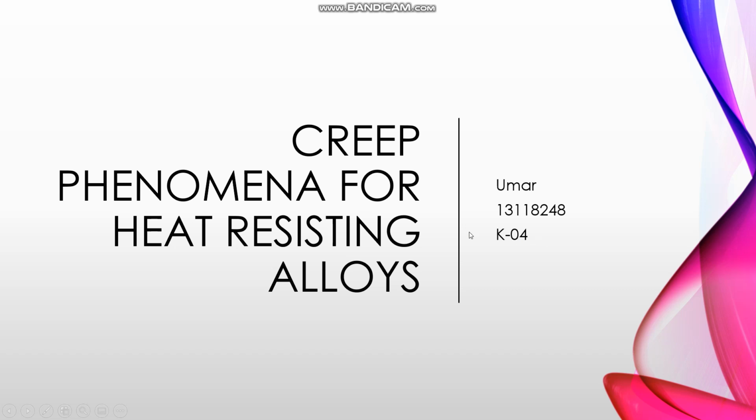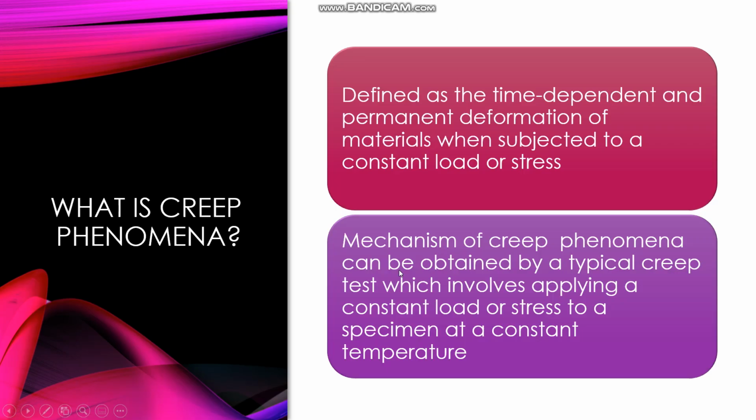Today, I would like to present creep phenomena for heat-resisting alloy. Before we move on, we need to know what is creep phenomena. Creep phenomena can be defined as the time-dependent and permanent deformation of materials when subjected to a constant load or stress. The mechanism of creep phenomena can be obtained by a typical creep test, which involves applying a constant load or stress to a specimen at a constant temperature.